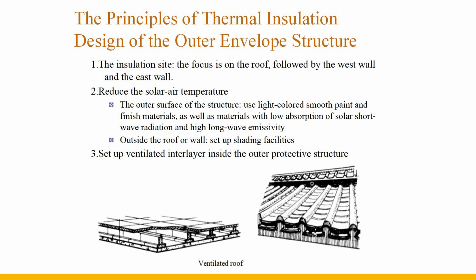The third, set up ventilated air layers inside the outer protective structure, such as ventilated roofs and ventilated curtain walls, using wind pressure and hot pressure to take away the heat in the air layer, thereby reducing heat transfer.